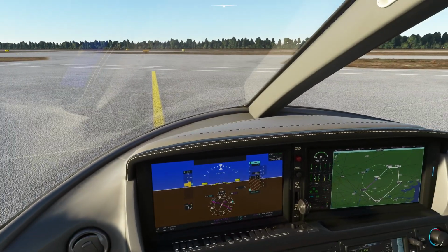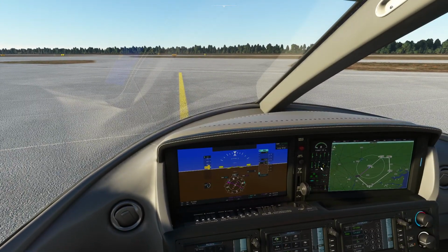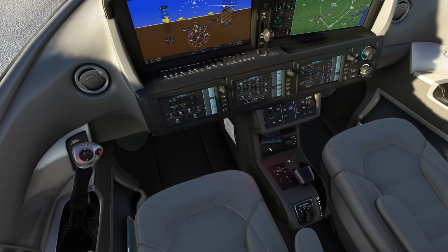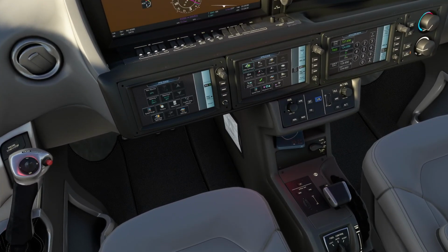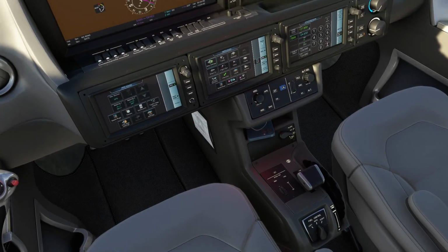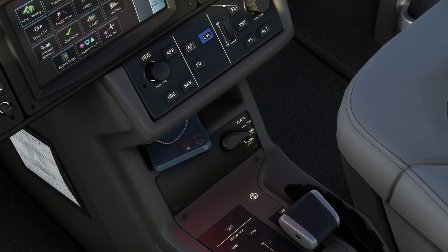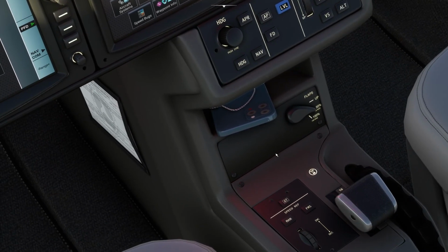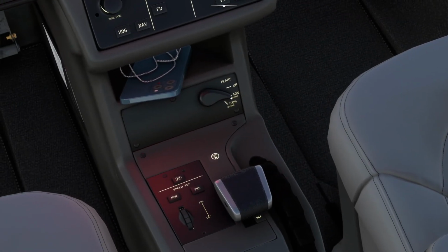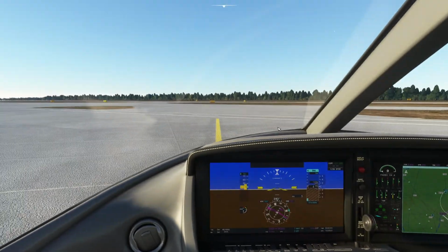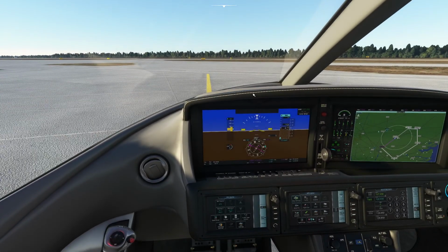Okay. Let's go and get this flight done anyway, just so you can see how the autopilot works as well. So come off the parking brake. Flaps to takeoff position, which is 50% I think in this aircraft. So we've got fuel control is auto. The flap lever is down here. So if we look closely at it, it's actually just got speed ratings for the various flap levels. So 50% it wants 190 knots. Oh, well, that's the maximum, 190 knots. 150 knots for full flaps.